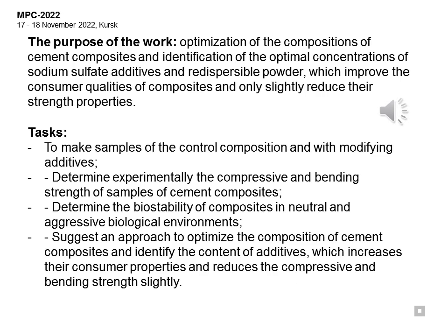Figure 2 shows line diagrams of equal influence of response functions, with compressive and flexural strengths of at least 85%, 90%, and 95% of the maximum compressive and flexural strength function. In Figure 3, the shaded areas guarantee compressive and flexural strength values of at least 95% of corresponding maximum compressive and flexural strengths. The choice of factor values from the optimal areas is carried out visually according to the diagrams and programmatically based on the properties of the patch function of the MATLAB system.